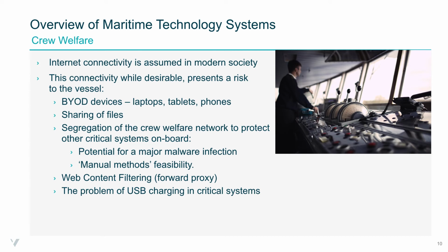Or similarly, if a boiler controller fails in the engine room, you would have a rating or an engineer manually controlling that boiler to continue to provide steam to the vessel. The problem is, as the industry's evolved, the skills to perform that manual role and the number of crew we have on board just will not support this fallback to manual methods. So it does present a significant risk to the safety of the ship.